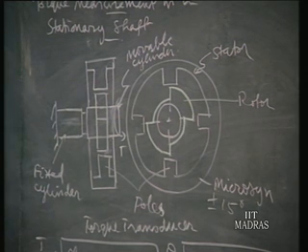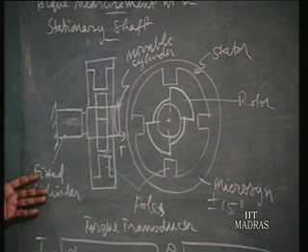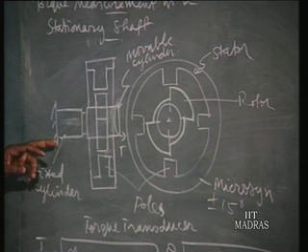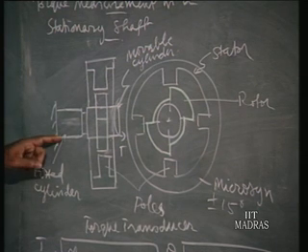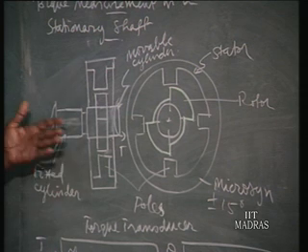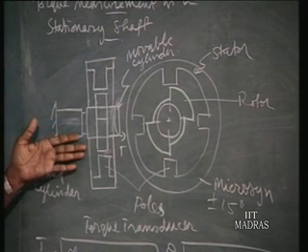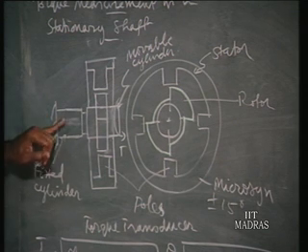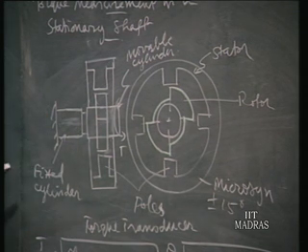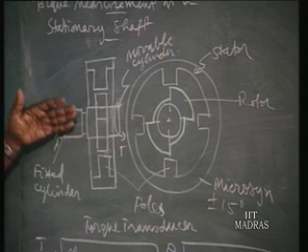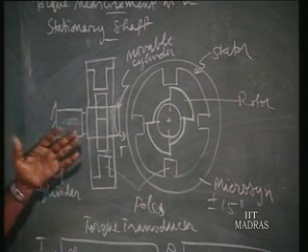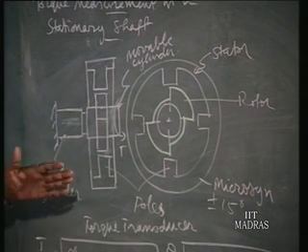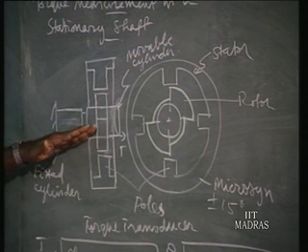We learnt about spring pivots, the cross leaf bearings, in one of the earlier lectures, as a way to reduce friction or play in bearings. So these 2 cylinders are connected by 2 cross leaf springs, the middle spring being twice the width of the 2 end springs. Springs are just flat spring steel material.